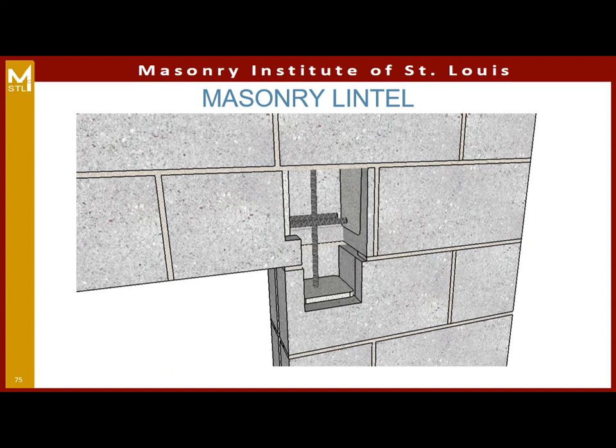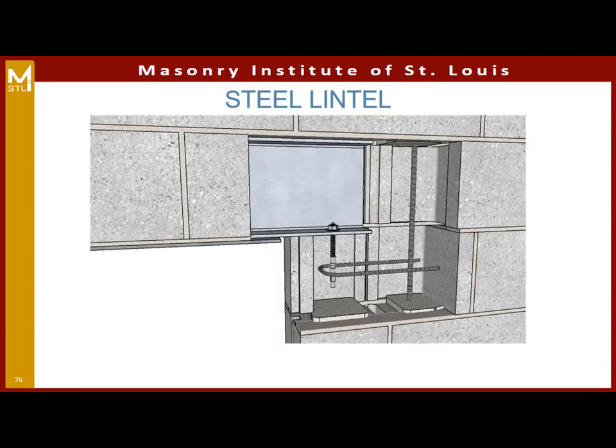So here's a cutaway view showing a little bit of the jamb steel issue that I was talking about. You can see how the jamb steel in that cell adjacent to the opening can run right through there and run full height continuous. Whereas with the steel lintel, we have to move that reinforcing back to avoid the steel lintel bearing. And you also see now anchor bolts and hairpins, maybe a bearing plate that's not shown there. So we get more things going on here.